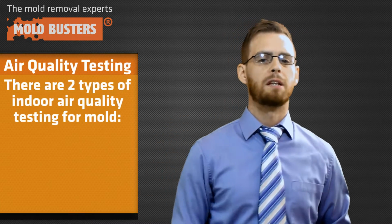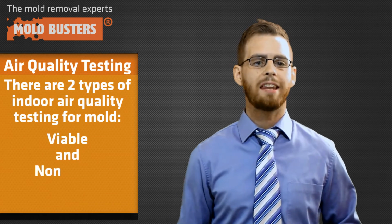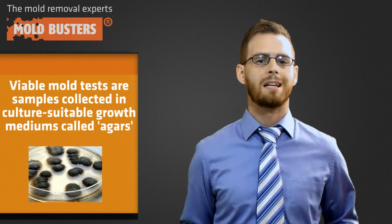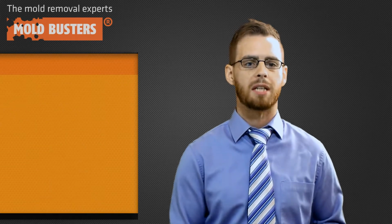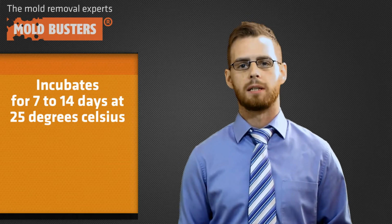There are two types of indoor air quality testing for mold. One is a viable kind, and the other is a non-viable kind. Viable mold testing uses specimens collected in culture-suitable growth mediums called agars. Agars are essentially contained in petri dishes and incubate for 7 to 14 days at 25 degrees Celsius.